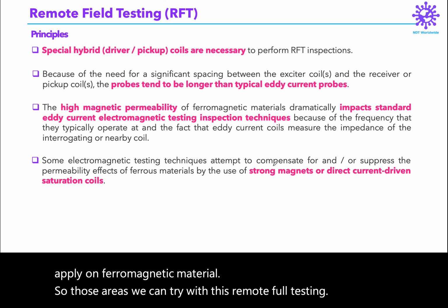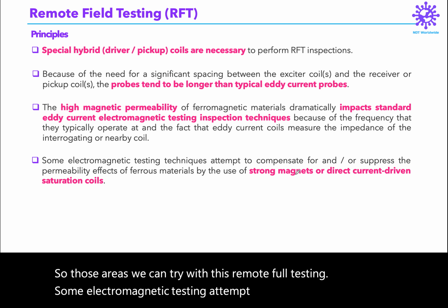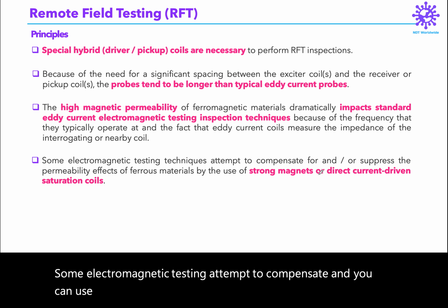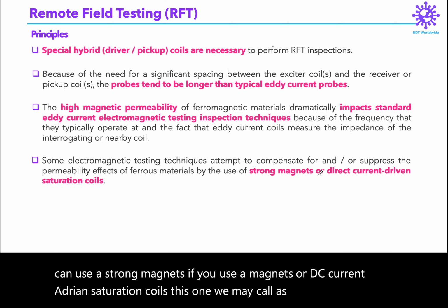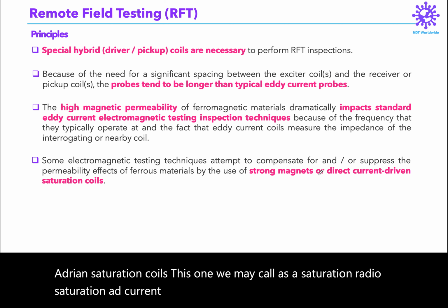Some electromagnetic testing attempts to compensate, and you can use strong magnets or DC current driven saturation coils. This one we may call saturation eddy current testing, and we can also use MFL tube inspection techniques.